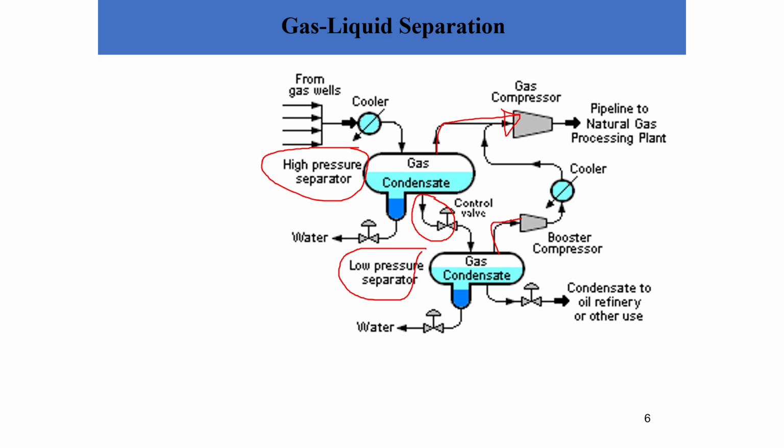This is a very appropriate and very profitable scenario, because most of the time you will optimize, or maximize, the separation of the gas from the liquids. But again, you have to look at the cost, because when you add further stages of separation, high combined with low, you are going to include more capital cost and operating cost as well. But you need to keep in mind that this will also result in a more efficient separation.